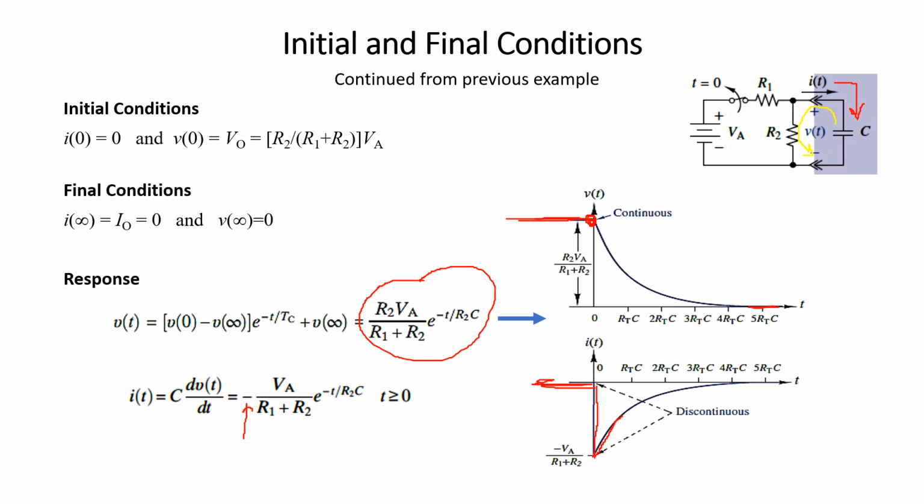So this is the initial value of the capacitor voltage, and just at the instant when we closed the switch, the current changes discontinuously. So the abrupt change of current is possible in a capacitor. The inductor is the dual of the capacitor: in inductors, sudden or abrupt change of current is not possible. However, voltage may change abruptly or suddenly in inductors.